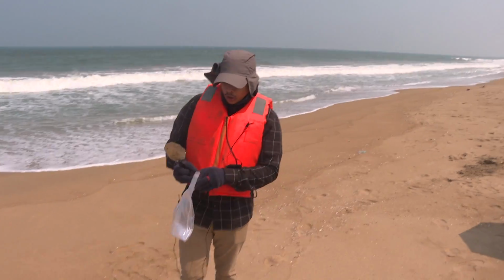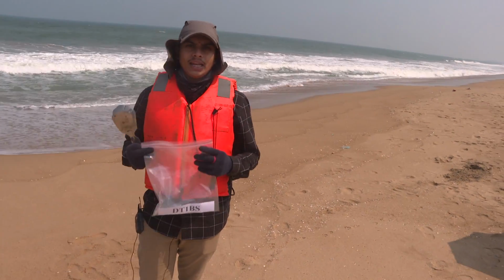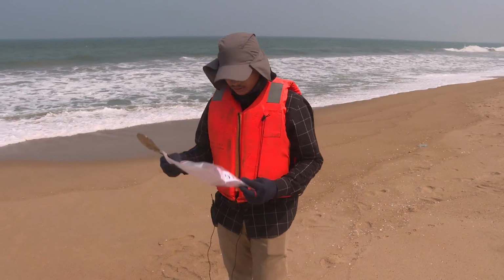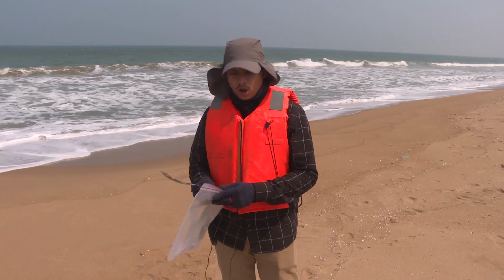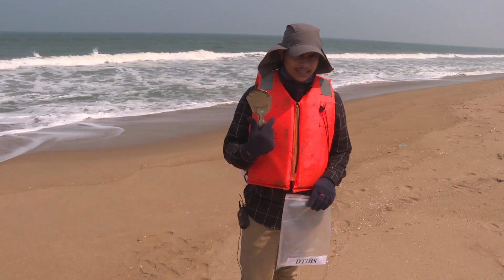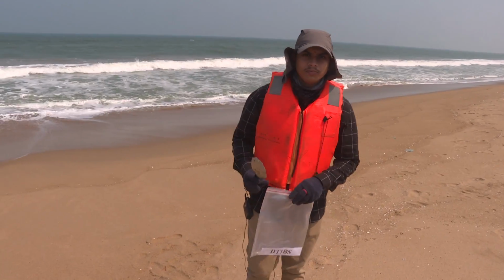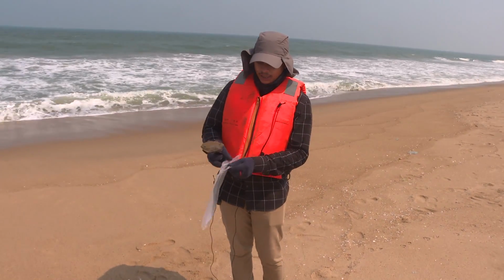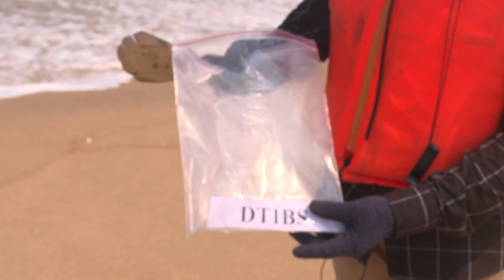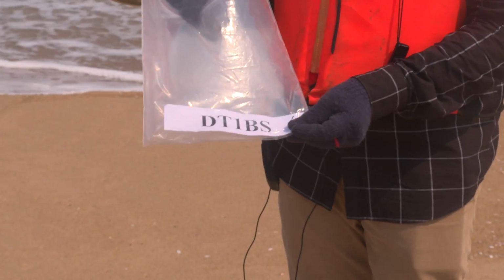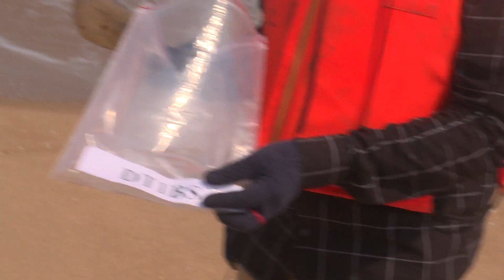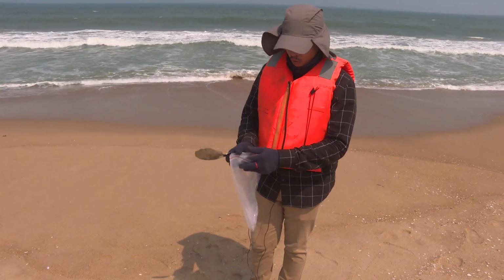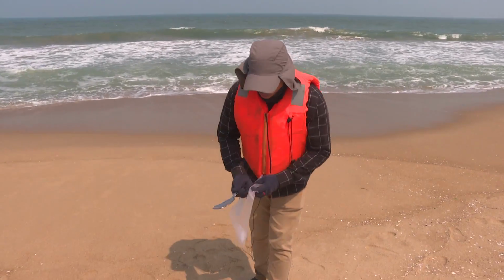In order to take the sediment sample, first we need a packing device, a package to seal the sediment. I have a Ziploc cover with me and a stainless steel scoop to scoop up the soil. I have two Ziploc covers, one kept inside the other, and a name tag denoting the soil and the location of the soil. I have kept this name tag in between the two Ziploc covers.